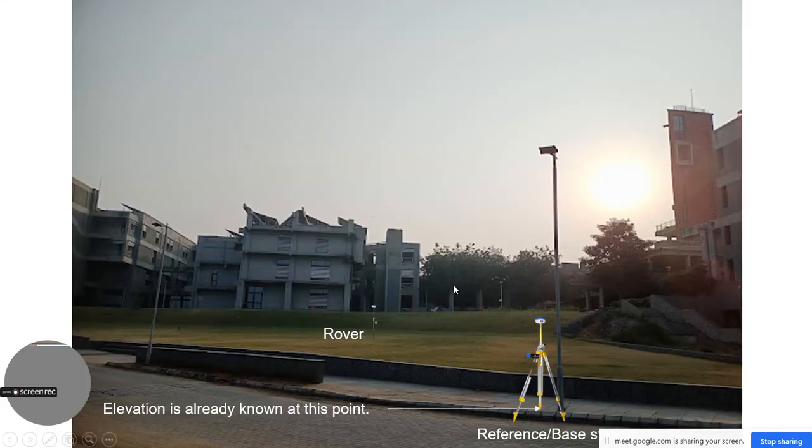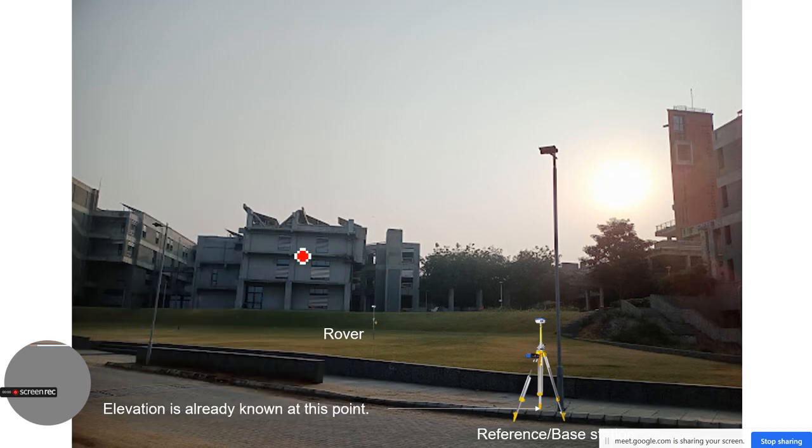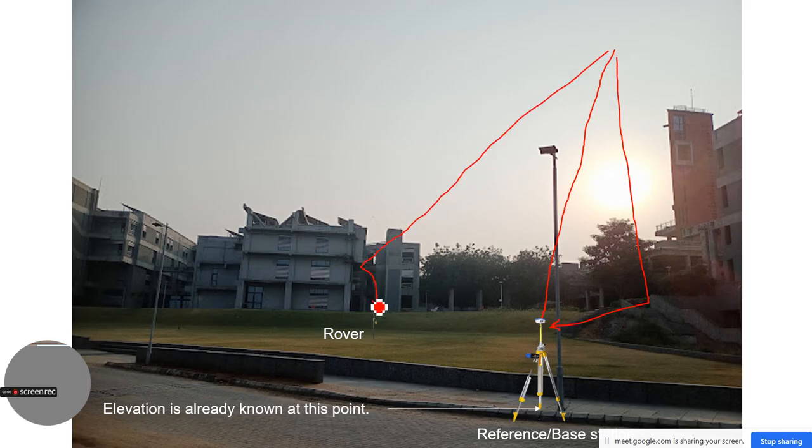So now you can see in this figure the base station and the rover station. Here, if a light or radiation signal is coming at the base station, it might interfere with this part and then be received over here. For the rover station, the signal will go to this building and then come to this. So this is multipath error.